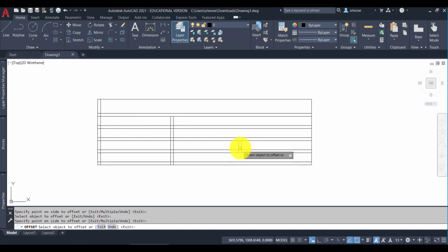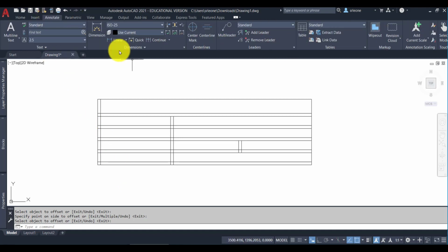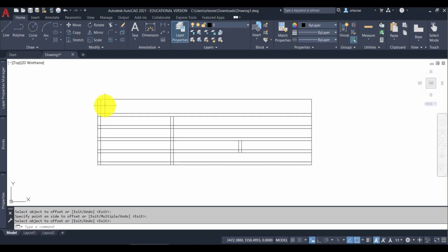Because we want everything to be in the bottom left corner of its space in this title block. Now I'm going to go ahead and delete these when I'm done using them to line everything up precisely, but we don't have to make a special layer or do anything like that. There's a special tool for that, but you know, just use a line. That's fine. Just offset. All right, so a text box.